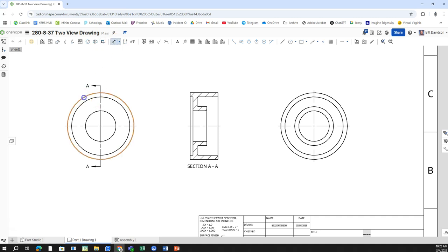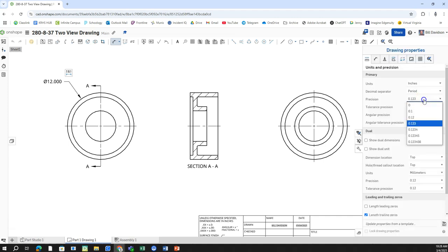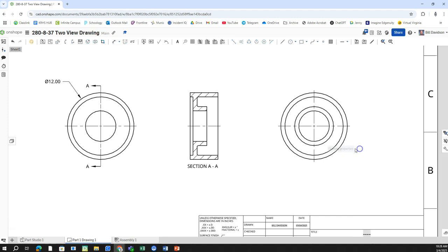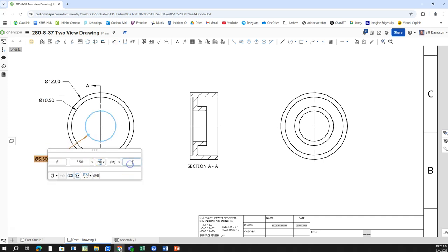I'm going to go ahead and put the 3 dimensions on here. Oh, we're going to switch this to 2 decimal places. If you haven't done that already, you should. 2 decimal places, and I'll put a dimension here, right here. I'll put that one on here, and I'll do another one right here, and this one I'm going to go ahead and click on this because I'm going to add space THRU so we know that goes through. Make sure your cap lock is on. Alright, so that goes through, so that's a hole going through it.